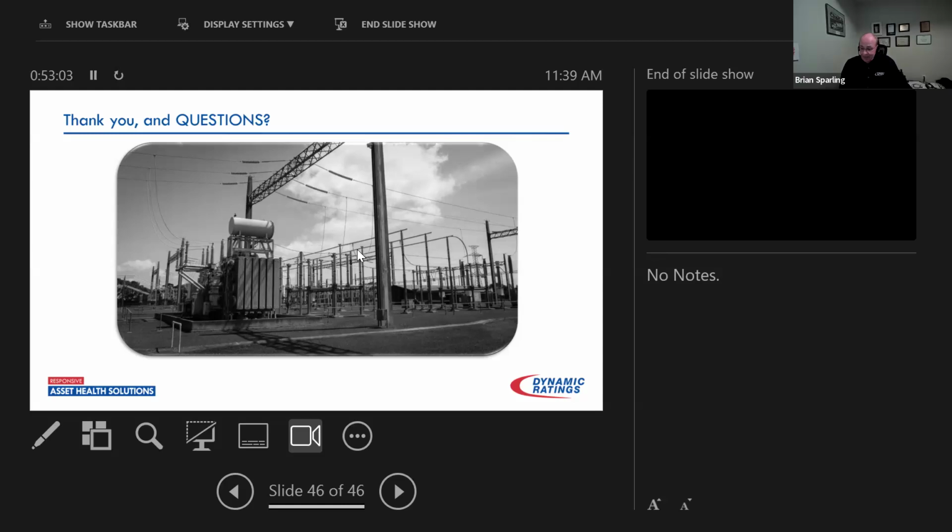And please give me an outage time. I got it within the next 24 hours, whatever. And now you're equipped: you get the outage, you get the right people, the right equipment, a spare bushing if you've got it, take it with you, and the test kit, so that you're making one trip to the substation to confirm the alarm and potentially fix the alarm there. That's the benefit of this. So automatic trip, not necessarily. That's what those protection relays are there for.